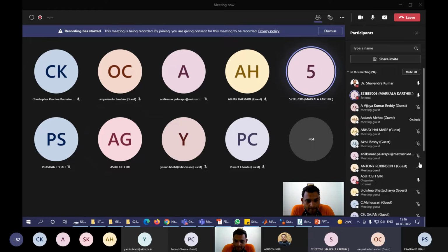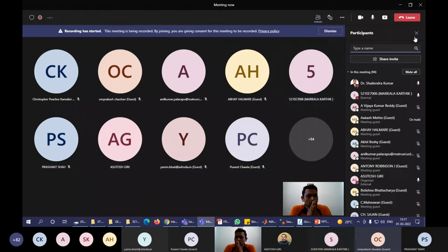Sir, one last query, sir. Yeah, please go ahead. Sir, during the simulation, what I observed, when I consider a three-phase grid, and when I started measuring THD of nonlinear load and grid side, what values do we have to consider for grid impedance, sir, R and L value, because it is showing some impact on THD value. That is what I observed.